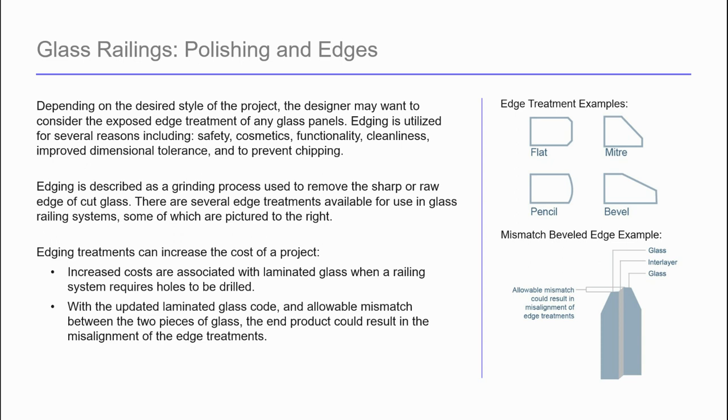So there's not only different types of glass and different types of inner layers, there's also different types of edge treatments. This is more on the aesthetic side. It does affect the stress level a little bit. Ultimately, flat polished edges are the industry standard. That also gets you slightly better behavior in the glass because you get rid of some micro cracks and discontinuities on the edges. Pictured examples of edge treatments are not common due to the increase in pricing. The miter, bevel, flat, those different treatments are not really common. They do cost a lot. But in general, you're either polishing or not polishing an edge. Not polishing an edge is usually one that's not visible, but you almost always polish them if they are visible.